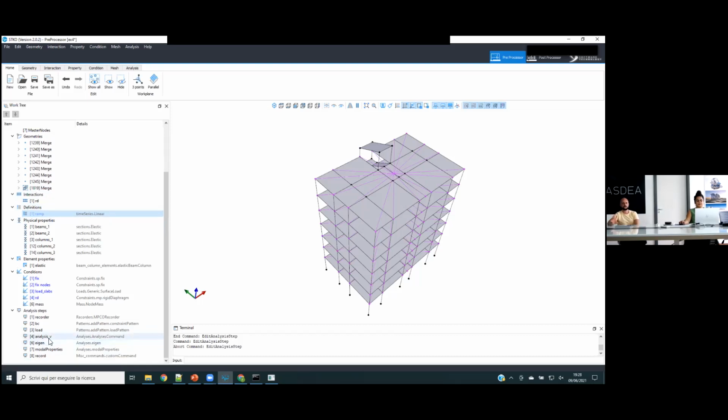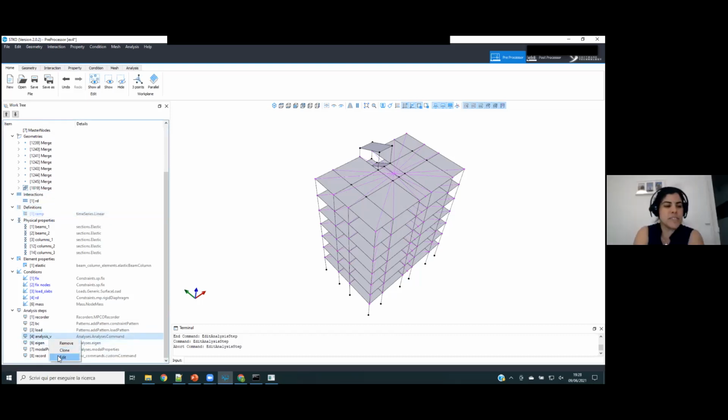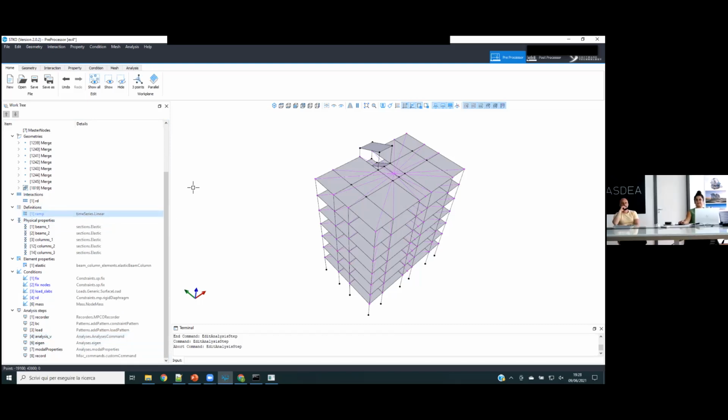It is a little bit confusing, but now it's better. Thank you. It's called time, but it's not just time. Yeah, in fact, if you monitor the time in a displacement control, you will see that the time is not monotonically increasing. It can decrease because it is actually the load multiplier. So it will increase up until the reference load can be increased. Then, if you have softening, you will see that the pseudo time goes back because actually it is not a real time. It is the load multiplier. Okay.